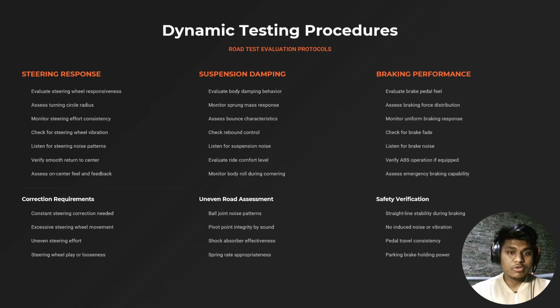During the road test protocols, I'm evaluating steering responsiveness and the vehicle's return to center. We monitor the suspension for body roll and shock absorber effectiveness on rough roads. Lastly, we verify braking performance, ensuring straight line stability and testing the holding power of the parking brake.